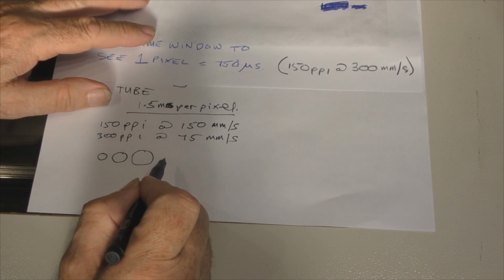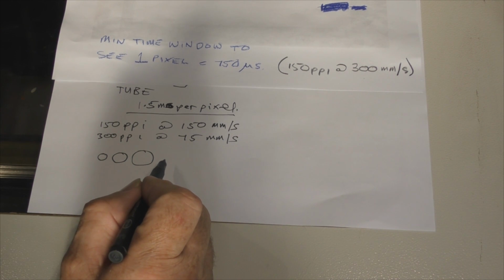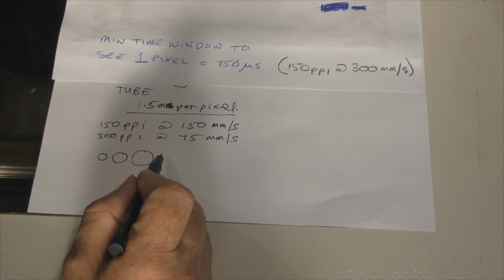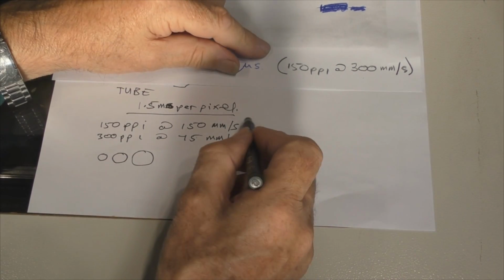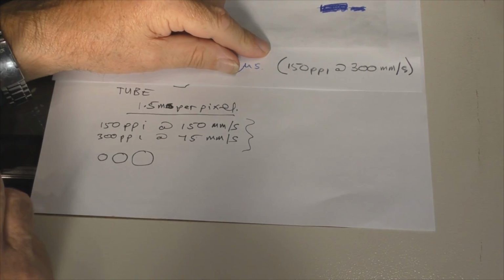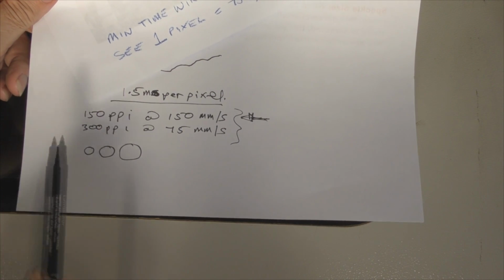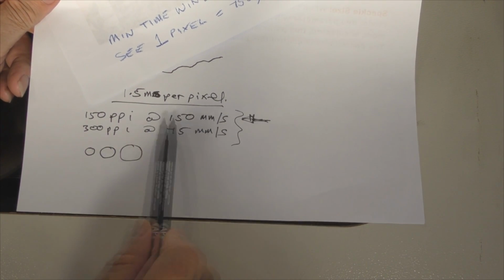But sadly, as you make the dot smaller, you make it less powerful because it's staying in one spot for less time. So consequently, the burn or the colour is less. This is becoming very complicated again. The only way to find out whether or not we've got something that's usable is to give it a try. But at least we know the zone that we can work in. So I'm going to run a trial at these maximum conditions.